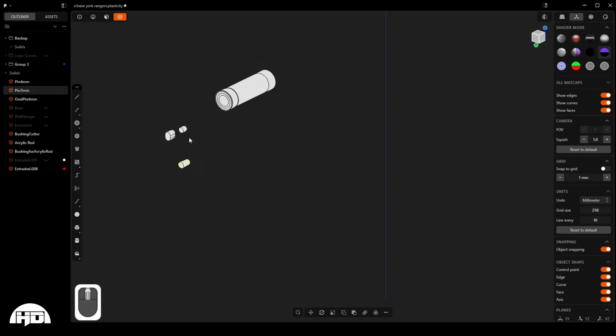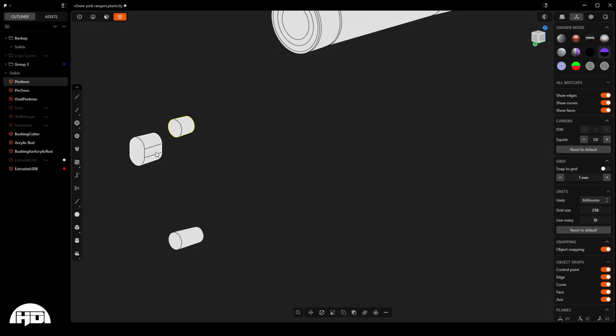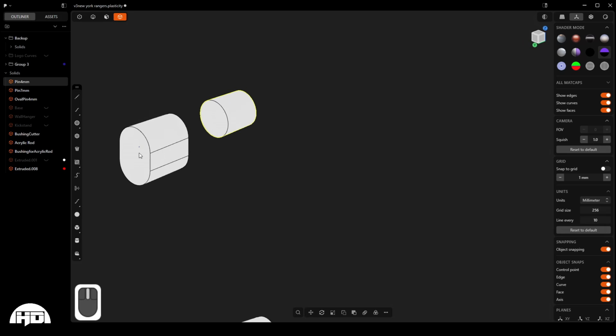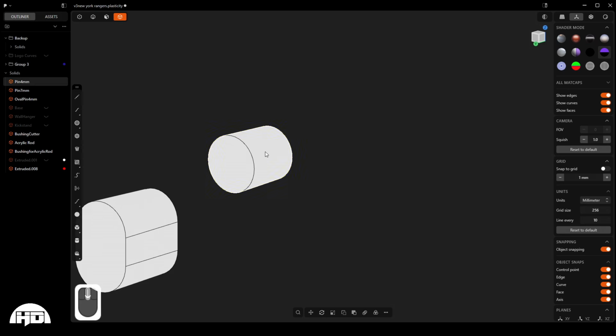So let's go ahead and do the same thing for the red. We're going to click the 4 millimeter. This one is a slot. So let's say that you did not have enough room to put two of these circles. Because it is a circle, if you only have one, that piece is still going to be able to spin. It's not going to lock in the orientation of that piece. So that's why I have this one, which is an oval. If you have a smaller area to work with, you can use the oval and that'll keep it locked in its orientation. But for this one, we'll have plenty of room to use the circles.